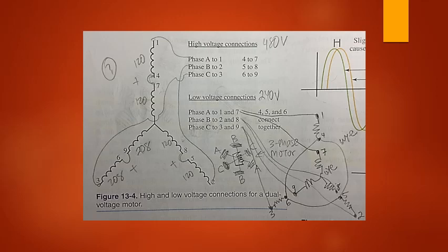To create a synchronous state with the stator, the windings on the rotor are energized by a DC source, and the rotor becomes an electromagnet. The rotor develops its own north and south pole, independent of the induction of the rotating magnetic field in the stator. There is no slip to maintain, thus the rotor travels at the exact same speed as the rotating magnetic field. This motor is used in applications where a constant speed must be maintained under a changing mechanical load condition.